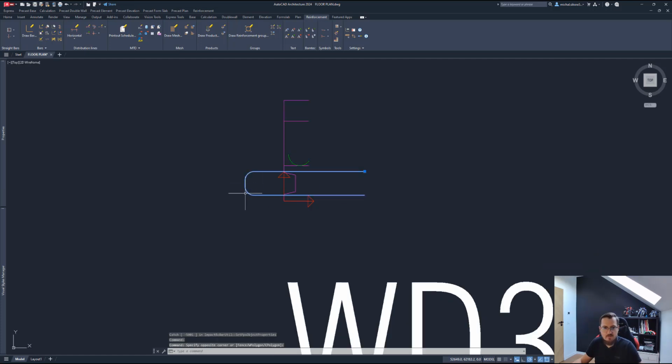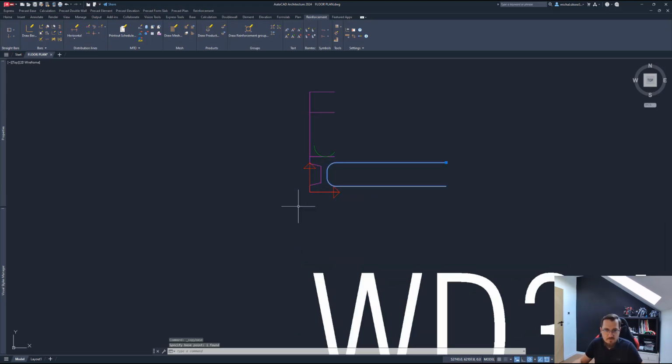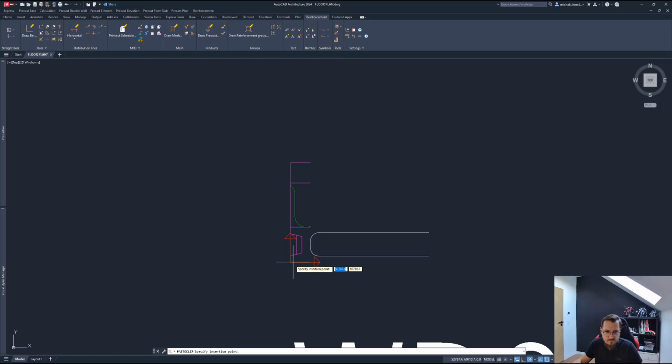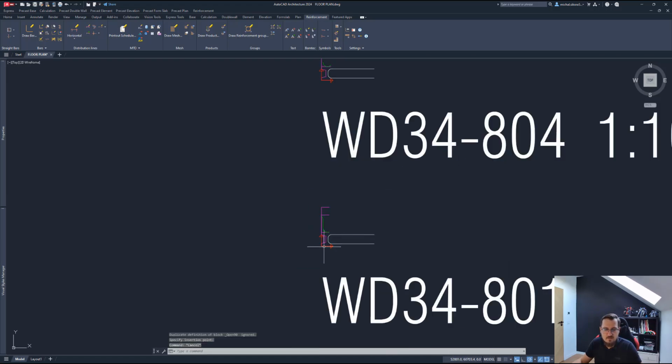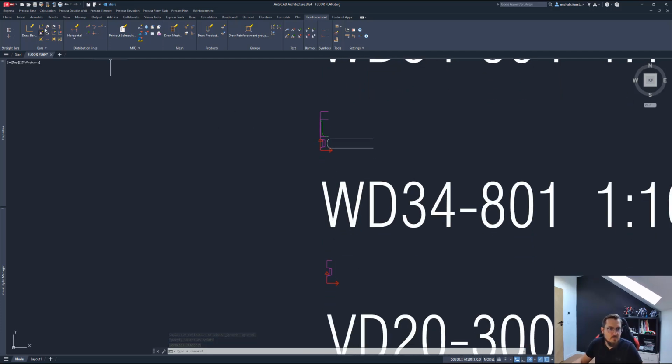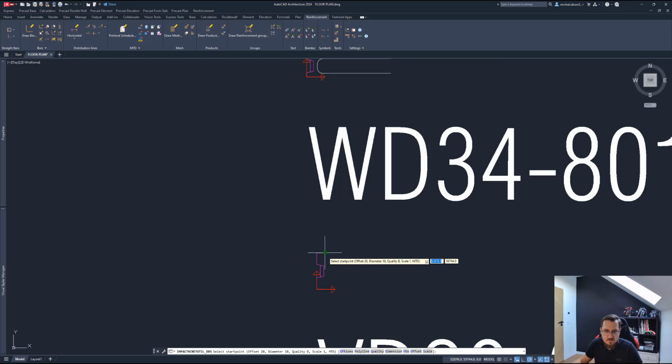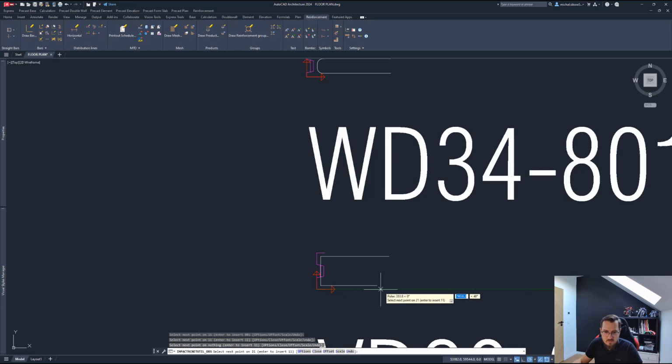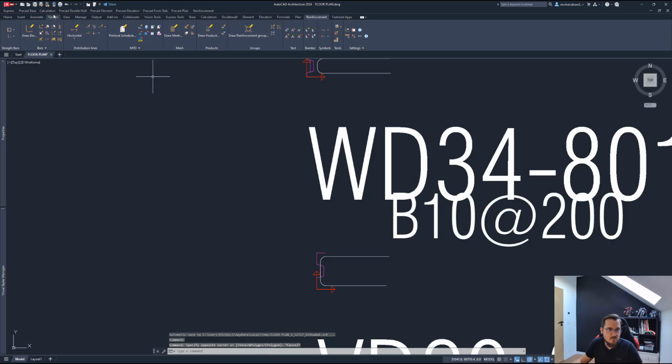And I'm going to move that bar. Right, I'm going to move that here and move that additional 20 mil like that. Also copy that bar and copy it here as well. So slightly different end cap, as you can see. What I will also do is very quickly create another bar for us like that. Click, click, click. I don't need to change any settings. Settings are remembered from the last bar. So let's edit that as well very quickly.